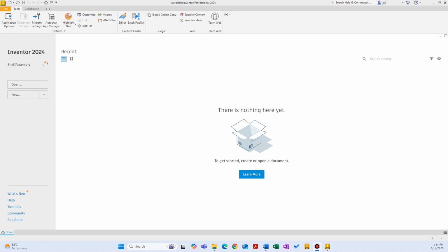As you know, in the previous video, we talked about the assembly mode, and now in this video, we're going to place components in an assembly. You're looking at the home screen of Autodesk Inventor Professional. As you know, we have multiple options to start a part or an assembly or a drawing. We can click on this drop-down menu and select assembly.iam. IAM stands for Inventor Assembly, just like IPT stands for Inventor Part. Also, we have this other option here. We can click on this drop-down menu and select Assembly, and that will take us to the assembly mode.